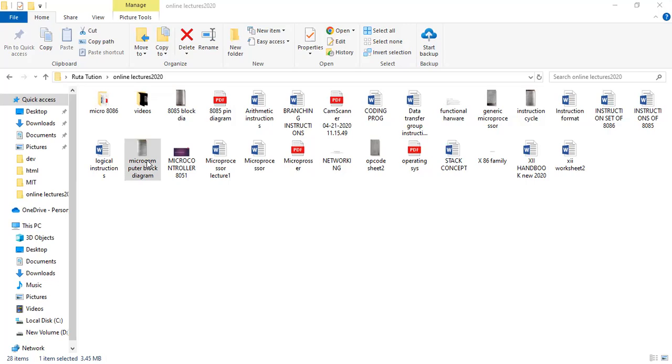For example, 0000 to 3FFF could be the address range for the keyboard, so for those addresses the decoder will send the chip select signal for the keyboard interface. For example, 6000 to 7FFF is a RAM area. In that case, if that address combination appears, then the address decoder will select the RAM.